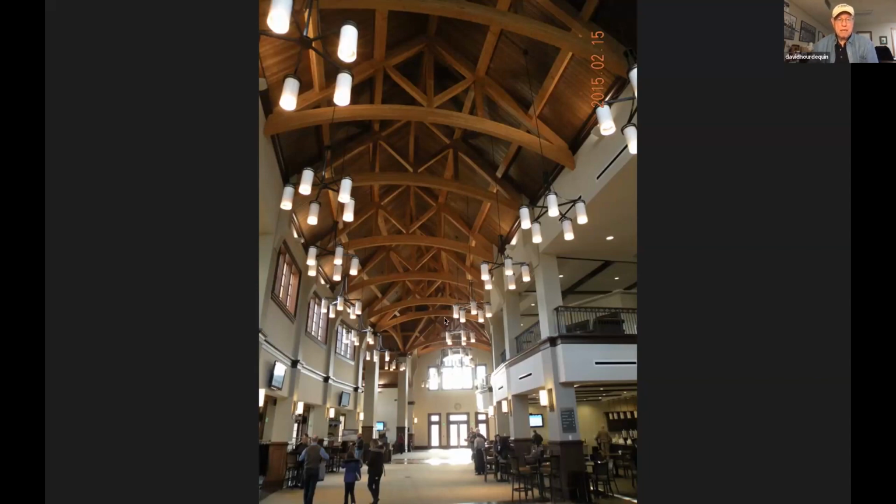This is in what they would call the narthex. This is a community church in Cincinnati, and interestingly, this wall was curved, but everything in here is square. So these are like chord segments, and you can see the arch members in here, and then back in this area, at the far end, you have intersecting gables. They're always a lot of fun, because the boundary of the intersecting gable, both the interconnection between the trusses and the trusses themselves, all form a tension ring for the load in the center of the interconnected gables, because the load has got to go somewhere, and so it's resisted by these ties in both directions.